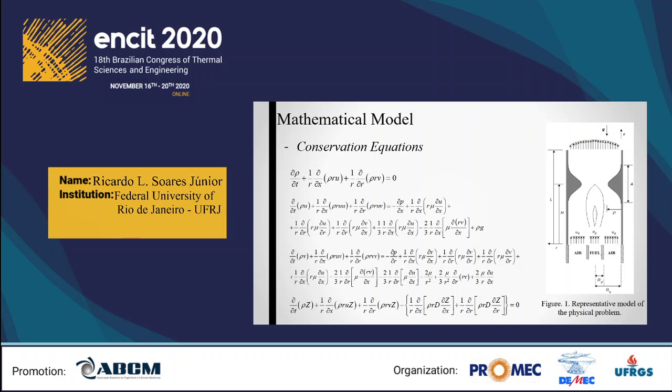Firstly, the thin flame hypothesis is considered. Also, the heat flux due to radiation effects is neglected. To further simplify the governing equations, it is assumed that dissipation by viscous stress and the flow work are negligible, as well as the Soret and the Dufour effects. Besides, the specific heat is considered constant for all chemical species, and the diffusion velocity obeys Fick's law. In this model, the chemical reaction is described by a single one-step irreversible reaction, corresponding to an infinitely fast conversion of reactants into stable products.